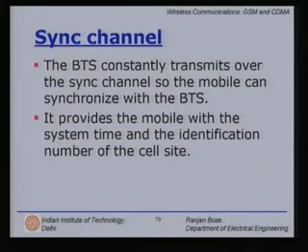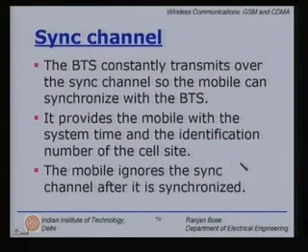It provides the mobile with the system time and the identification number of the cell site. So, it is primarily used for time synchronization. The mobile ignores the sync channel after it is synchronized. So, it transmits a set of known patterns by virtue of which you synchronize, basically lock in.